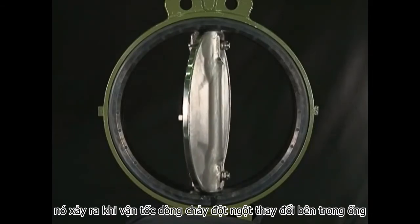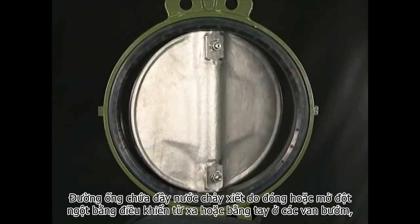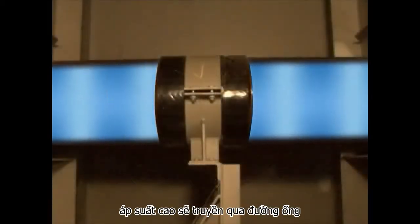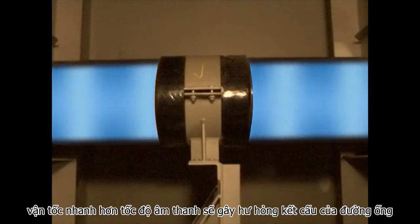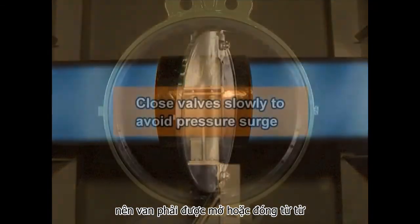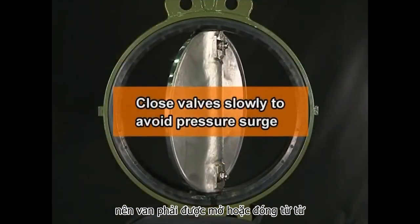It takes place when the flow velocity suddenly changes inside the pipeline filled with fast-flowing water due to abrupt opening or closing, whether remote or manual, of butterfly valves. In the event of a pressure surge, a high-pressure face propagates through the pipeline at a velocity faster than the speed of sound, causing damage to structural parts of the pipeline. So valves must be opened or closed slowly.